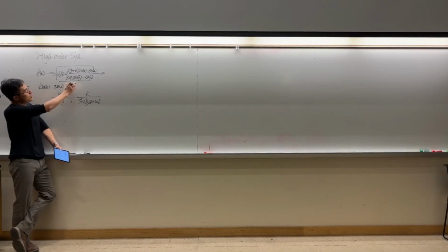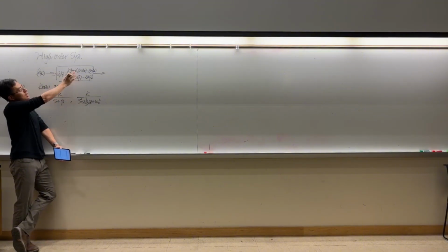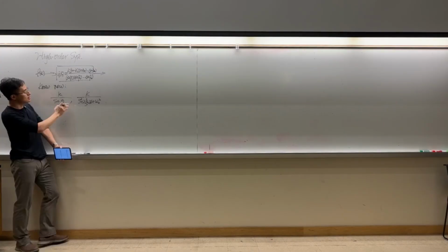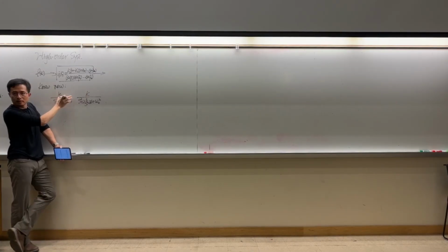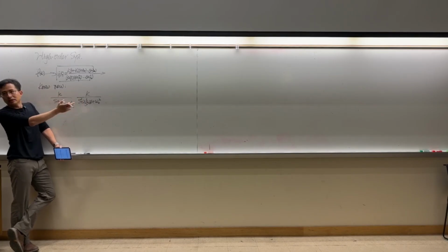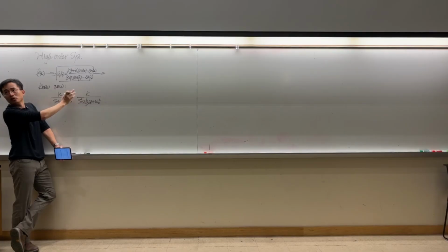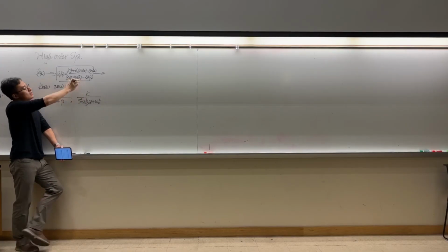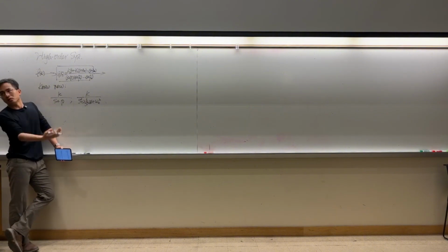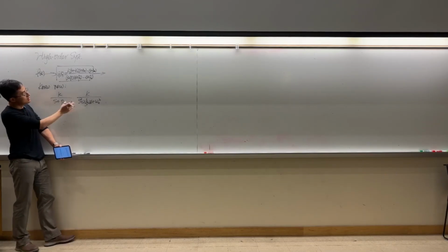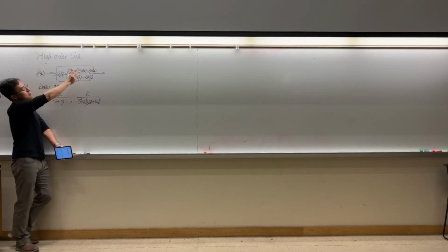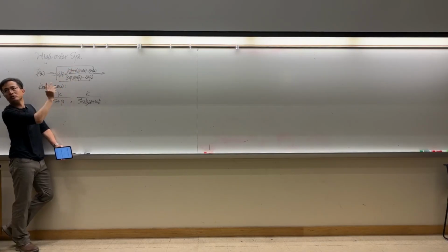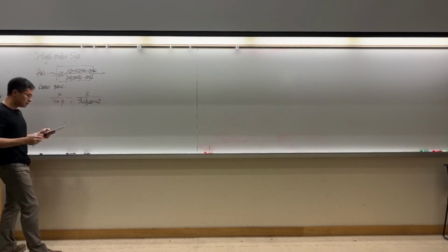First, we definitely have more poles. So we need to think about how, when these poles combine together, the response will look. Second, what we have talked about is that the numerator is relatively simple. All the two cases that we talked about don't have zeros. For a general system, the zeros will also play some role. So what we're going to do now is first go through the step of just combining the poles, make the zeros simple, and then we generalize from there. So that's the general thought process.